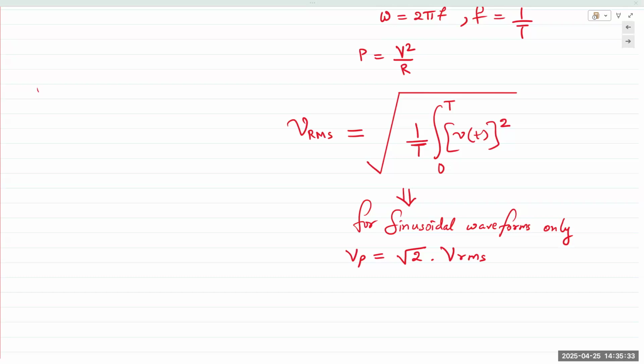So 60 times in 1 second, the power outlet is going from 0 to plus 170, then back to 0 to minus 170, and then back up to 0. So the full swing of 340 volts. So RMS values, why do we use peak?